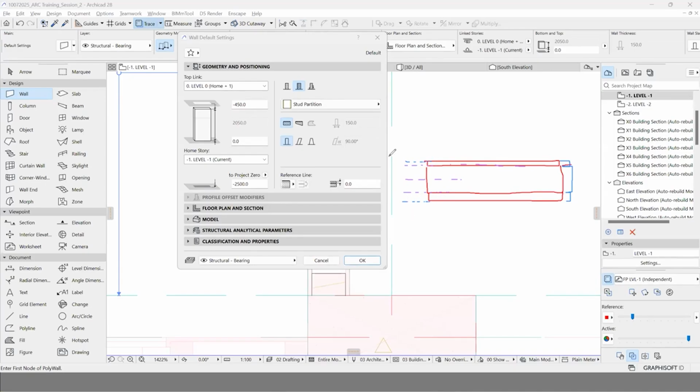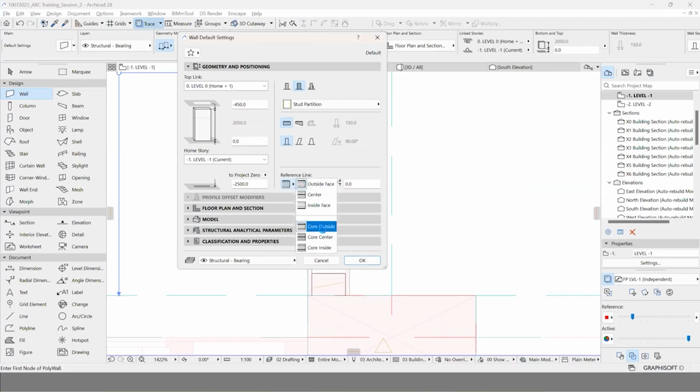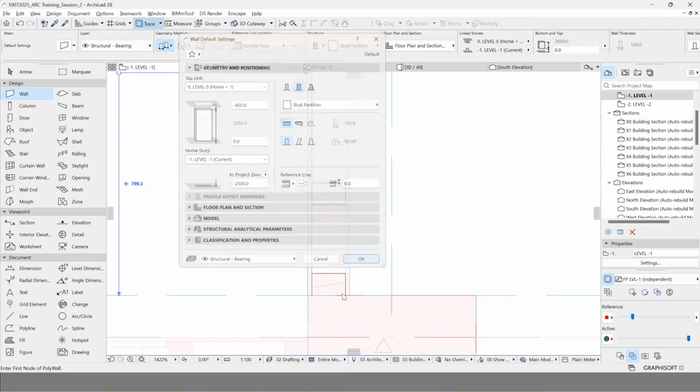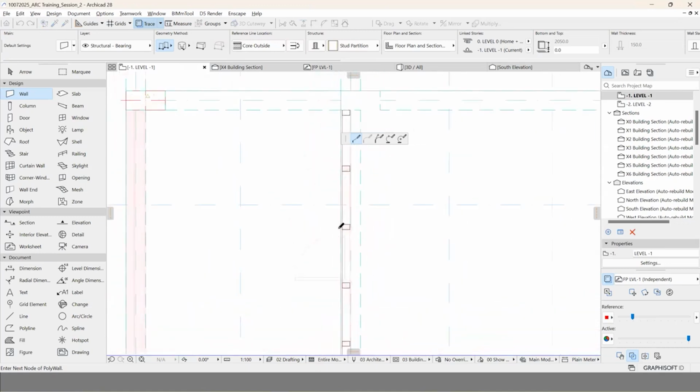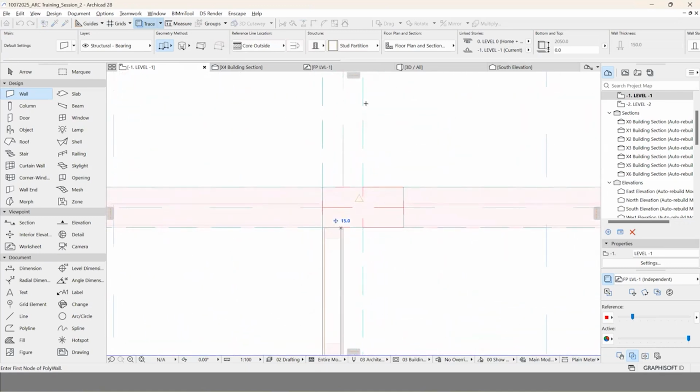So you'll get multiple options for the line. So what I'm going to select here is, because I know all the options in this, I could just go for the core outside instead of face itself. And then I can draft from here, because this is right now the core part where the cavity is. And I can draft it from here to here.